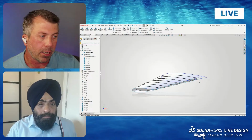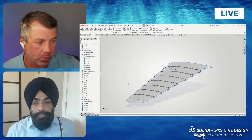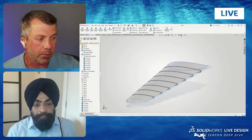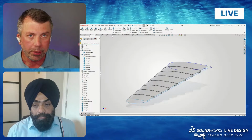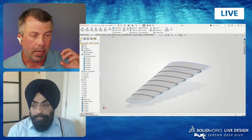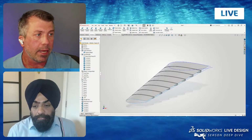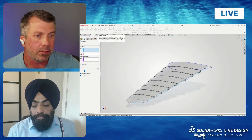That's why I cut the back off, because I would redo this for the tail end section. You still have the spar to add to it. Obviously, we have to do some lofting if we're going to have whatever the end or capping looks like for the wing. But what's really slick is at this point, since we have really good curve geometry coming in because it's an equation-based curve, healthy geometry coming in, we've got a surface body that's generated essentially with that, is we can come back through and use this surface flatten tool.